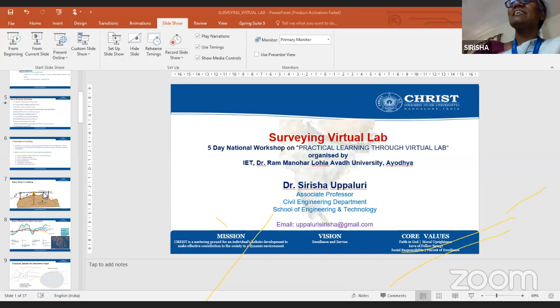But the arrangement is like that so that it won't go deeper. Wherever we have fixed it at a 6 feet level, it should stay at a 6 feet level for several years, hundreds of years. That is the concept behind fixing the GTS benchmarks at 6 feet below the ground level, so that nobody can tamper with those benchmarks. But we have lost so many benchmarks over the years.